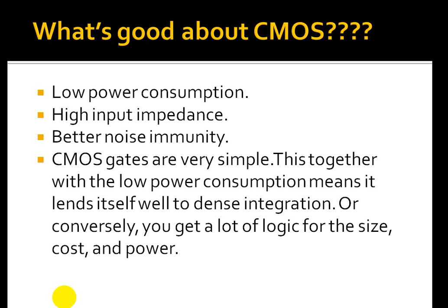Then, CMOS always has a high input impedance, so it draws almost zero current from the driving gate, and therefore its fan out is very high. Also we can see the high noise margin, which means that a signal which is logic 1 with finite noise added to it is still recognized as logic 1 and not logic 0. In both low and high states, the noise margin of CMOS remains the same, which is 30% of VDD.